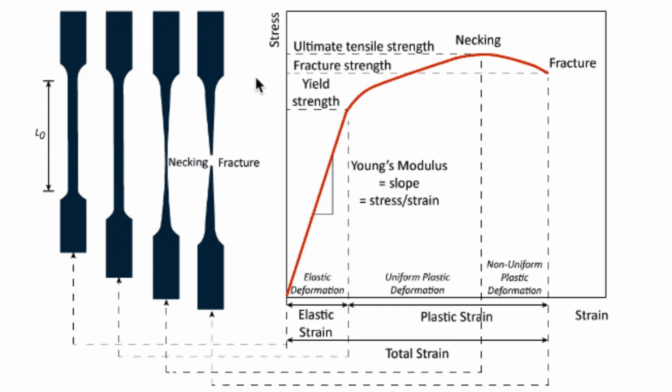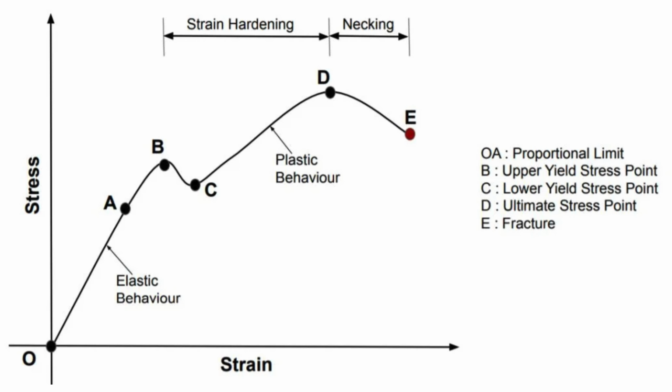on unloading. The residual strain induced by a given stress can be determined by drawing an unloading line from the highest point reached on the stress-strain curve at that stress back to the strain axis, drawn with a slope equal to that of the initial elastic loading line. This is done because the material unloads elastically, there being no force driving the molecular structure back to its original position. A closely related term is the yield stress.